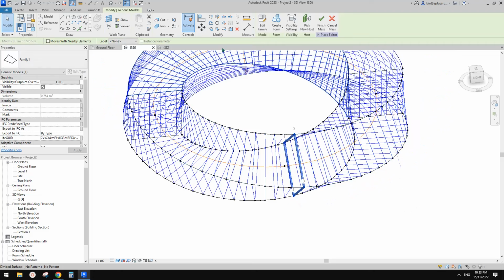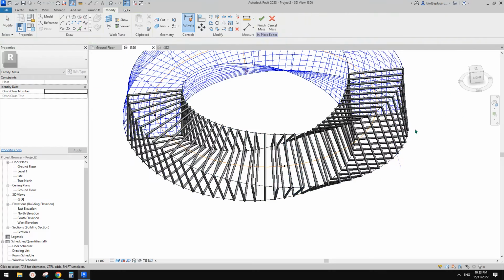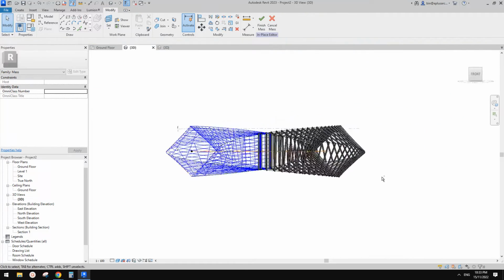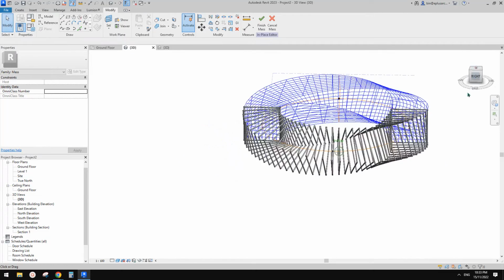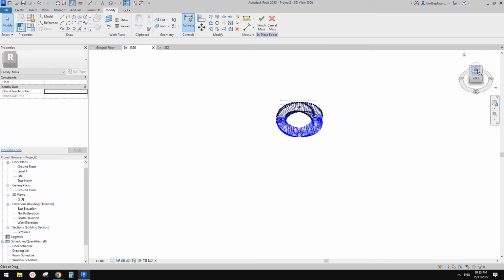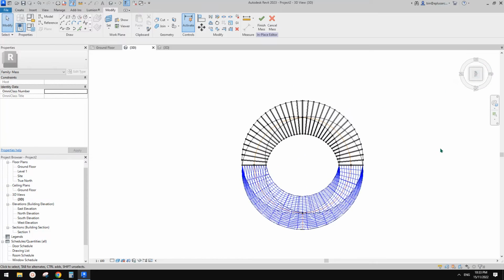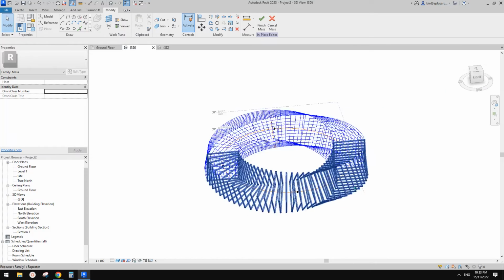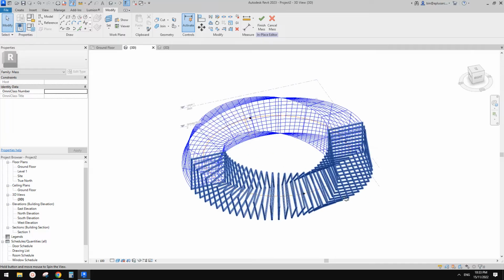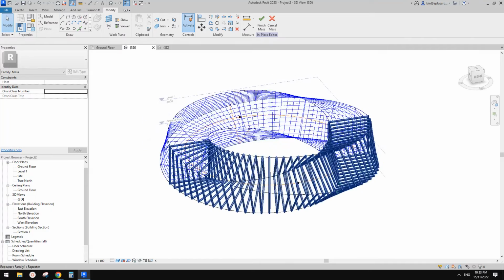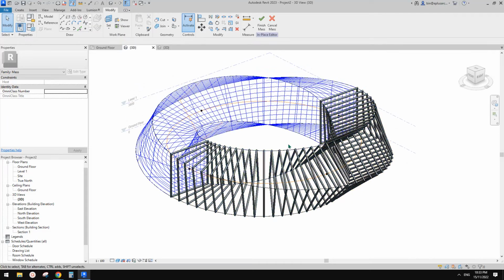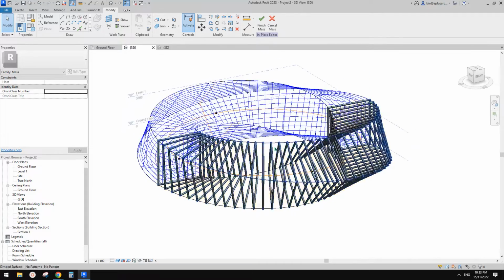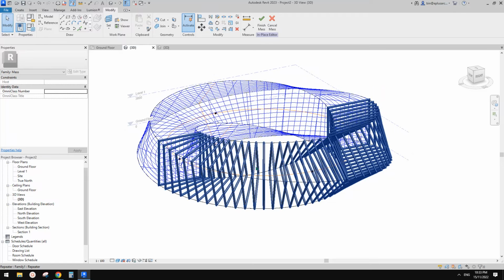So now you can select this one, click on repeat, and that's all the frame we need. Right, so go to the top to double check, so they are all vertical, and that's it. And so something extra, so if you want to place some glazing between these, how can we do it? So yeah, it's quite simple.